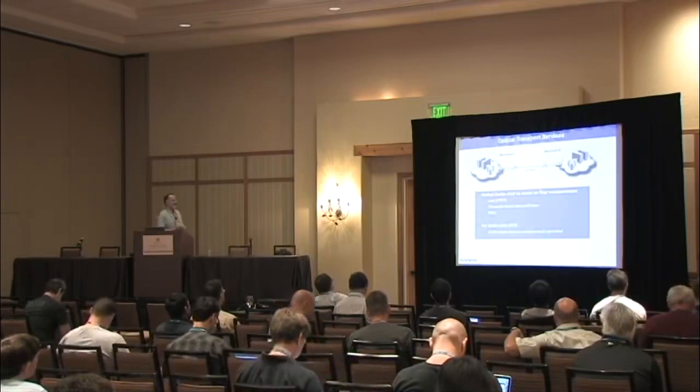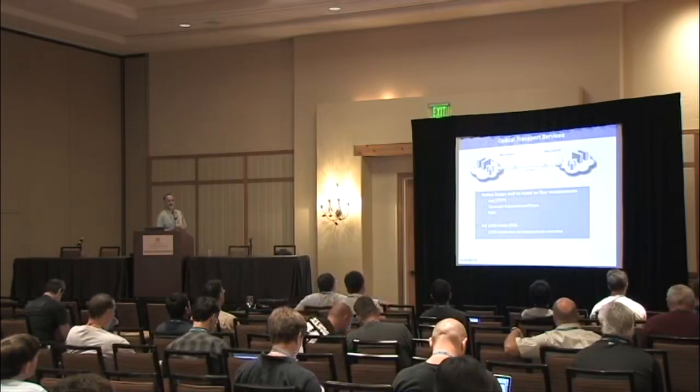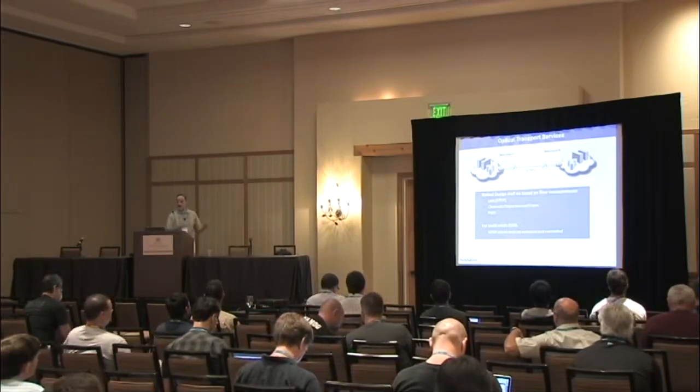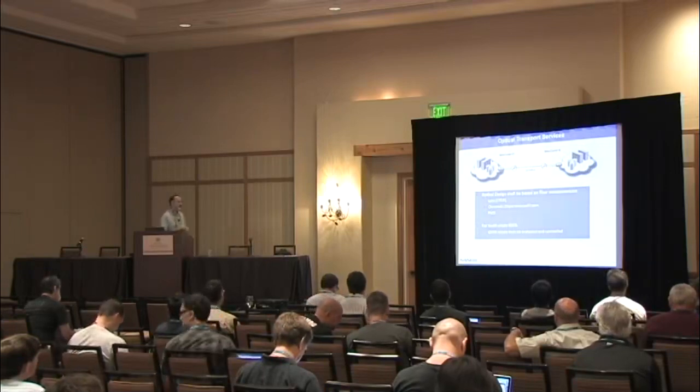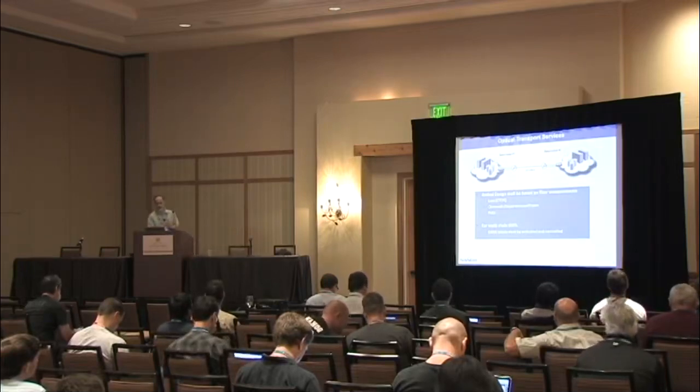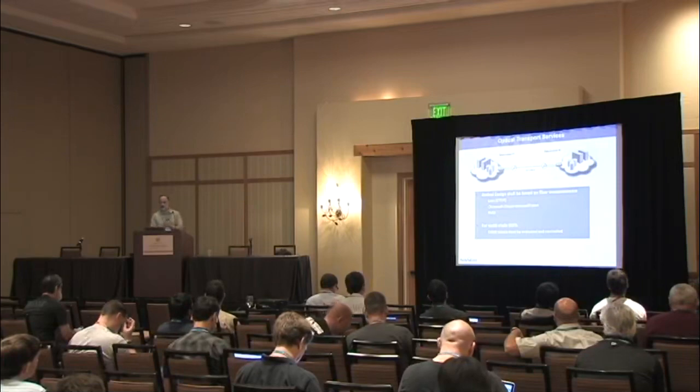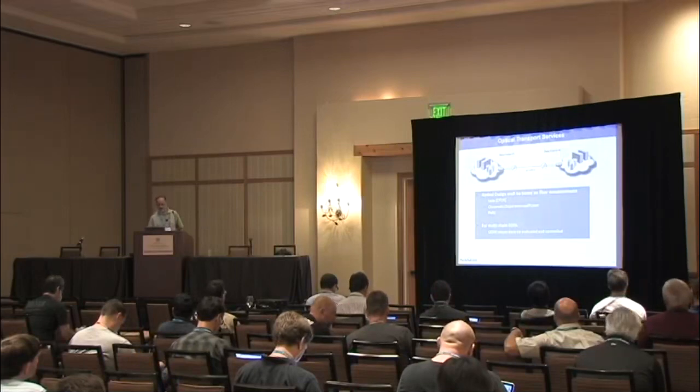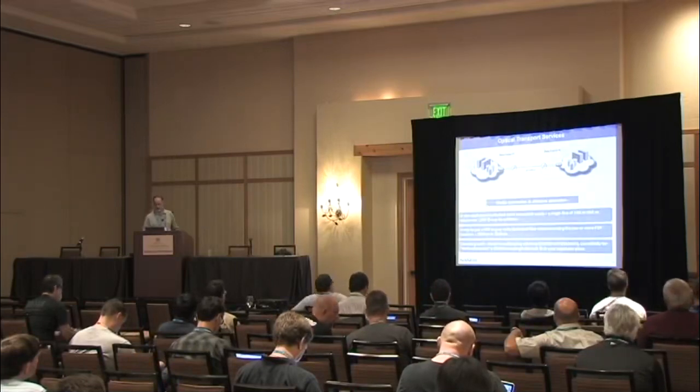In general, you must base your design on optical design and on fiber measurement. Do not just look at kilometers like we are going to do now. Measure the fiber: get an OTDR, measure your chromatic dispersion coefficient, measure your PMD. And for multi-chain EDFA, of course, OSNR values, optical signal to noise ratio, must be evaluated and controlled. We are not going to talk about this because that's a little bit beyond this presentation.